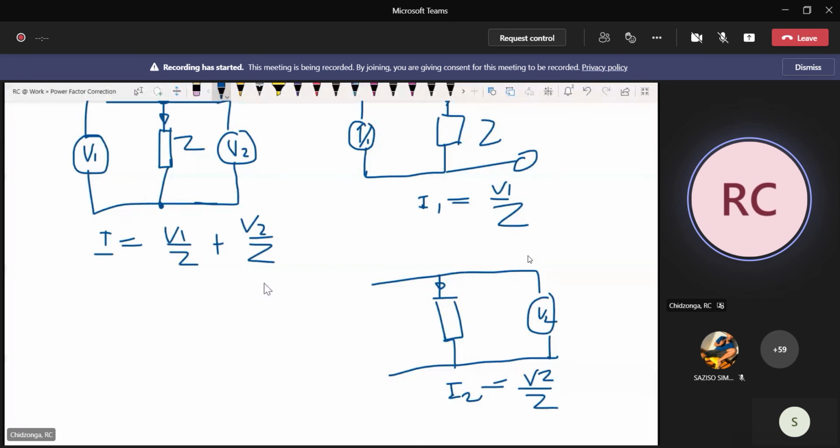The net effect of the flow in a particular element, in a particular branch, when there are a number of sources: calculate whatever variable you are worried about due to that one source, disconnect that source, add another one, calculate, and then at the end, add the net results of those calculations. You are going to get the result of having all those sources connected at one time. That is what we call the superposition principle, right?